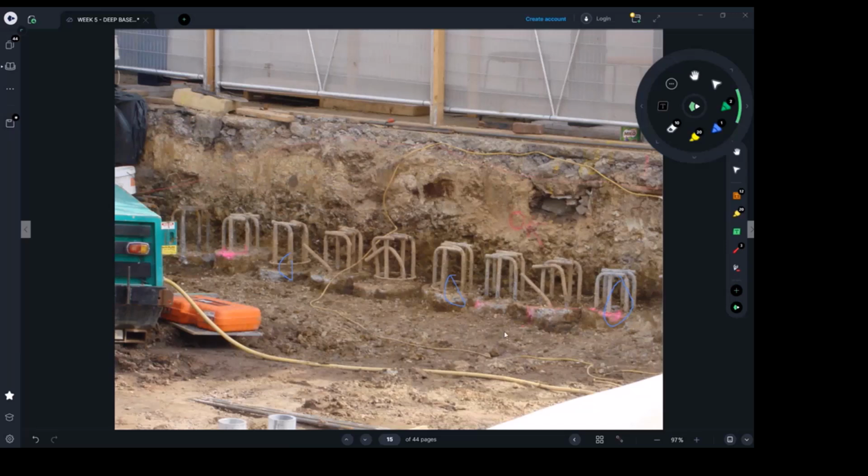Definitely the builder wants to do them closely spaced because he just wants to smash it and finish this job and get paid for this part of the construction. But again, it depends on the soil condition. I would say every fourth pile, like every blue one here.